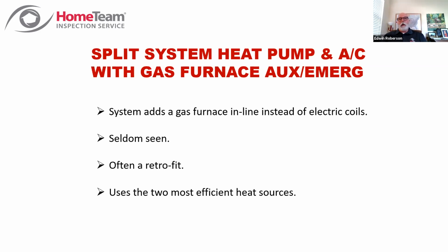It's not a bad idea. It's more expensive because you've bought more equipment, but it would pay for itself over time because you're using the two most efficient heat sources. You're using a heat pump when your temperature is high enough that it can do the job, and then you're using gas, which is, I say, the second most efficient. Gas is way more efficient than a heat pump once the outdoor temperature gets so low.